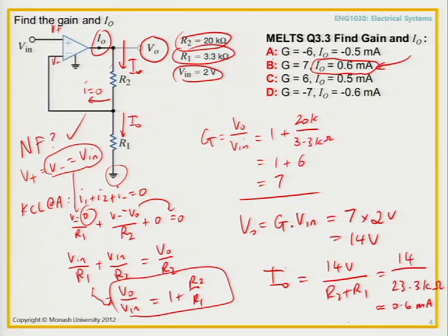What's really happening here is that the op amp is adjusting the exact amount of current coming out of here to make the voltage at V minus equal to whatever voltage it sees at V in. That's basically how the op amp works when you've got negative feedback. If you don't have negative feedback, the op amp doesn't know what's going on, and it can only operate in that mode that we saw yesterday, on Monday, which is that differential mode.